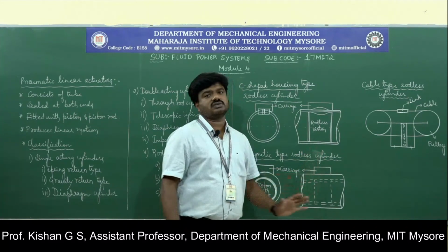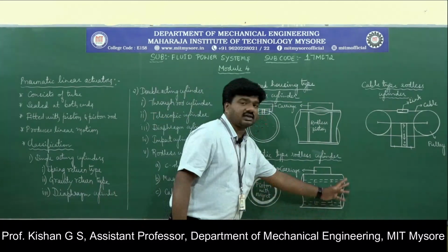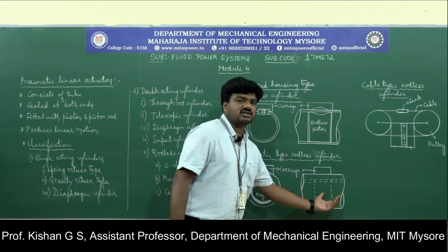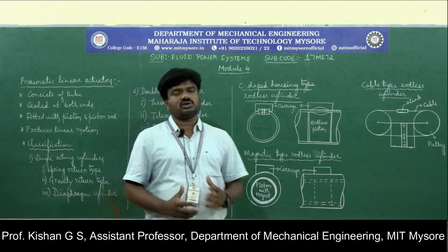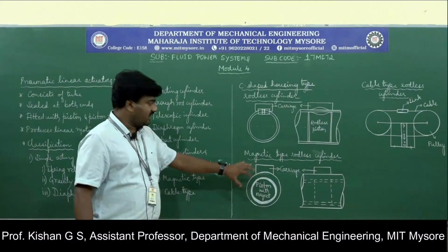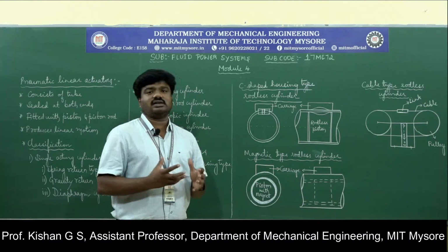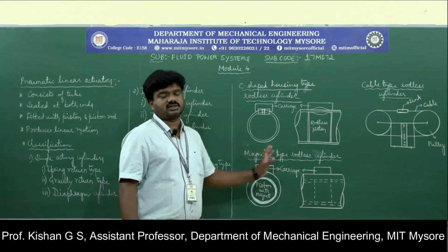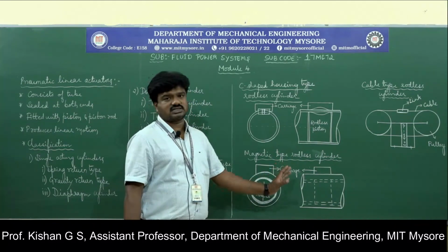from left to right because of the magnetic pull, and when it has to be retracted, the supply from the other end of the cylinder leads to the movement of the rodless piston from right to left, and the carriage assembly moves along the same path due to the magnetic pull. Since the piston consists of a magnet, the carriage assembly which houses the external load is magnetically attracted, so the movement of the piston with magnet leads to the movement of the carriage assembly. This is one type of magnetic rodless double acting cylinder.